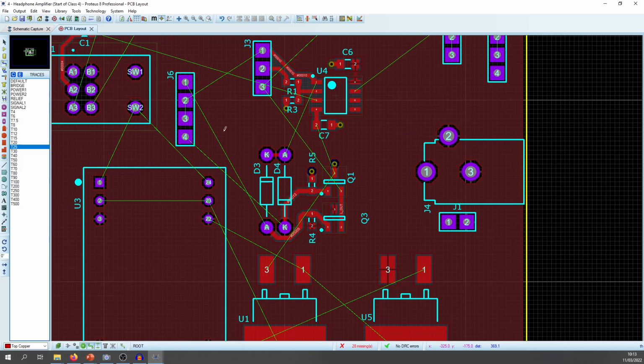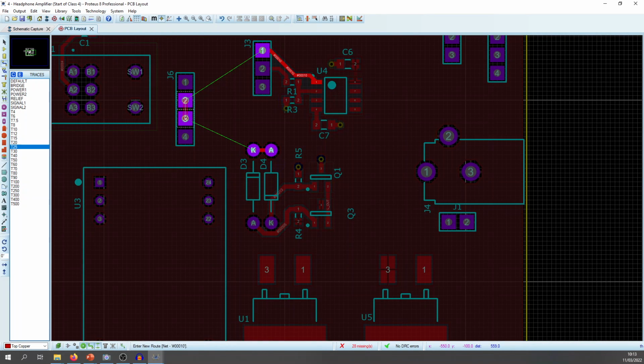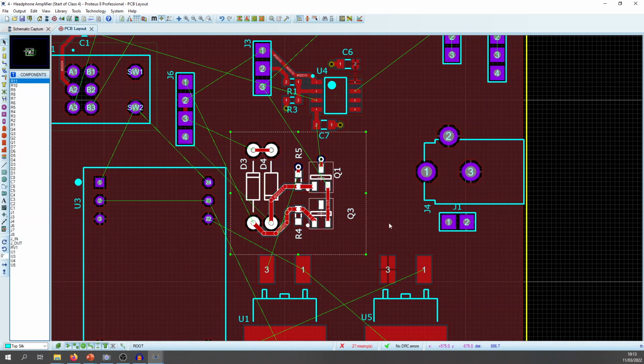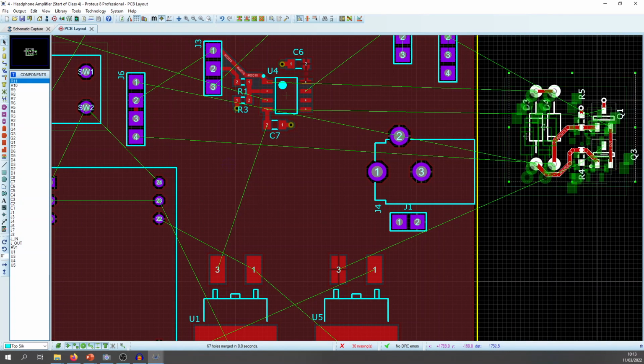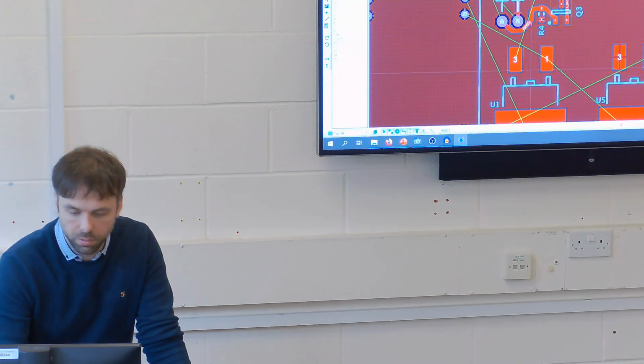So you can see now we can start to build up these sections, and to connect this lot to the rest of the circuitry, you'd essentially be going through here. And then again, these jumps here are slightly larger. So again, I'd refrain from doing these big jumps until you're happy with where this little module, let's call it, or this little collection of components wants to be. Because what you'd do is you can keep that as it is. It's nice and neat and a little compact cluster. And then you can do the other channel. It's got two channels. So just do the two channels and then you can slowly work through it like that.